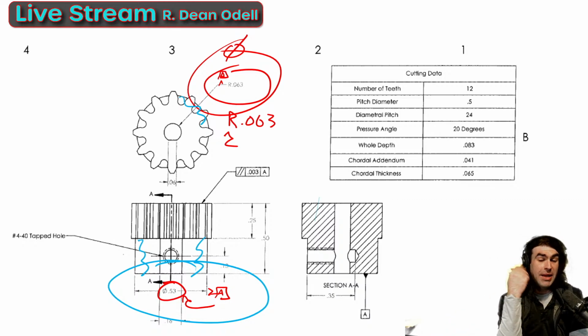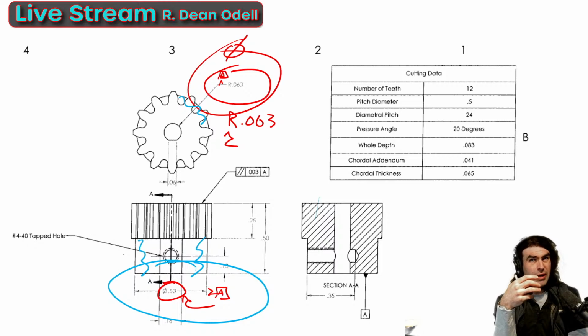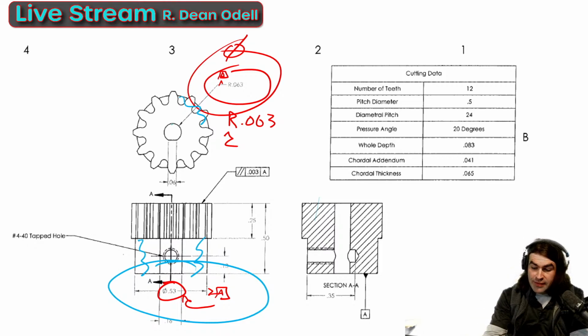Maybe it's used in the manufacturing process or something. So I want to bring that up because you've got to be able to explain these decisions to people, right? What sets the orientation of the part in space? It's this thing that a shaft is fitting on, not this larger cylinder that is just mating to air. Okay.